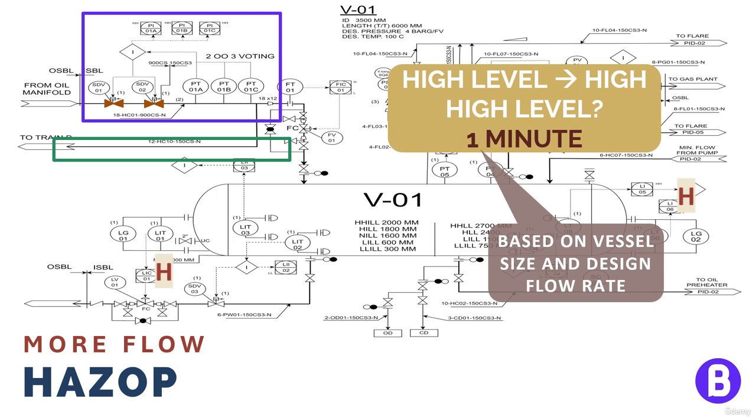And if we added a shutdown valve to stop the flow to the inlet vessel after FV01, this shall also be a source of overpressure, which we were already trying to reduce its frequency.